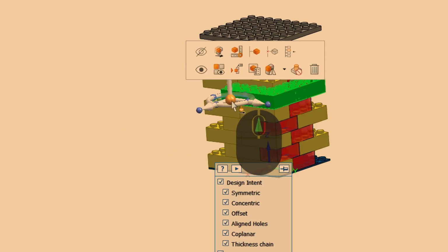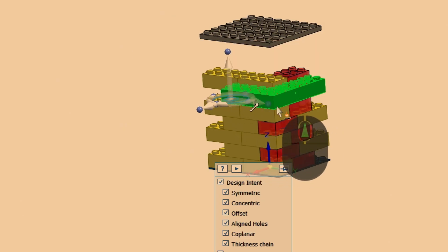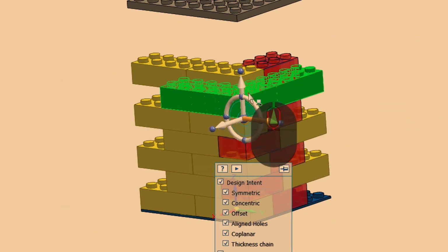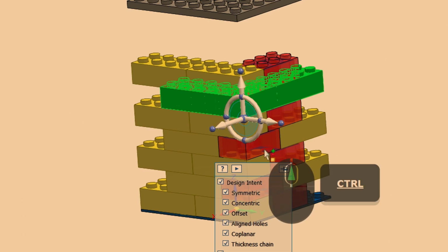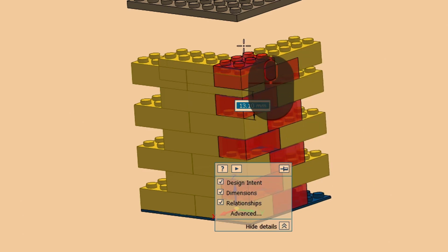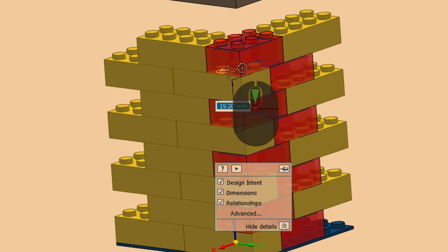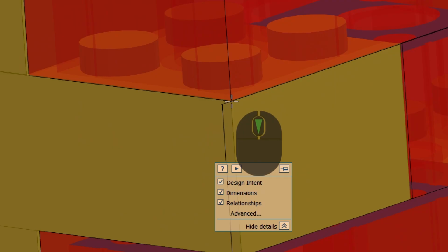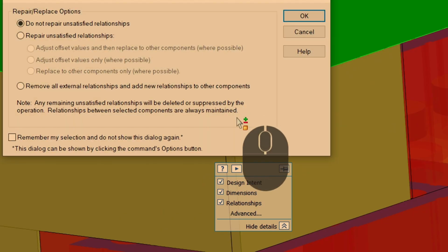So I'm going to choose this part and this part. I'm going to move our steering wheel, click on the center of it, go over to this corner and locate it there. So that does two things. That creates our base point that we're copying from, and it also orients it. So it aligns this vertical line with the vertical line on the blocks. So I'm pressing the control key again, click on this arrow on the steering wheel, and that's copying those vertically along that line. So all we need now is the point to copy them to. So I'm going to choose this corner of this block and click there.